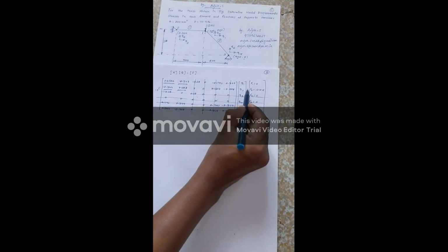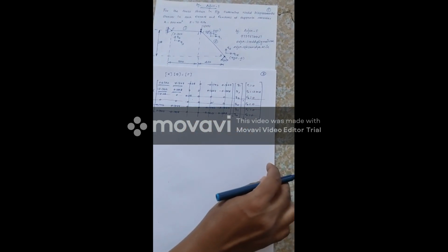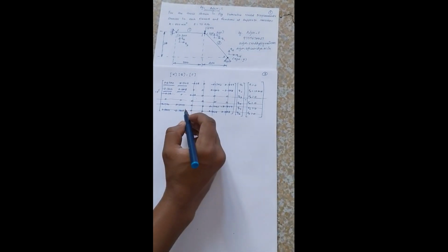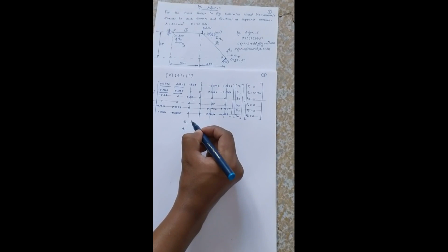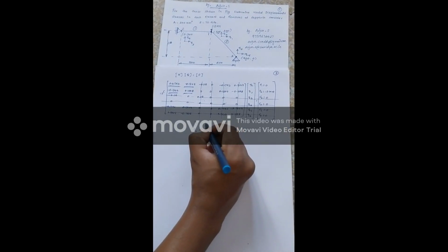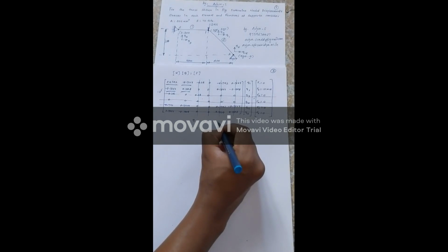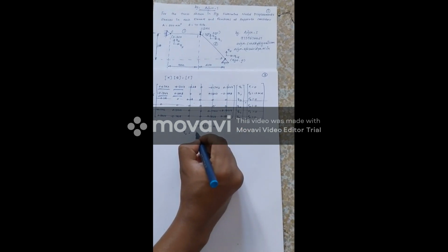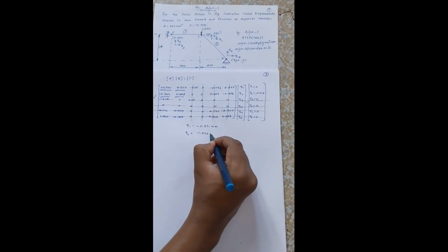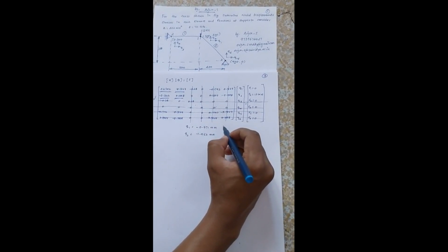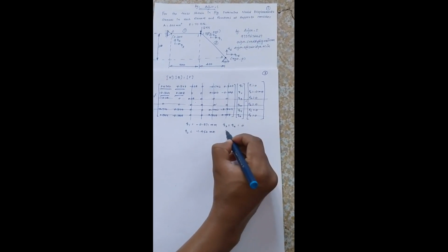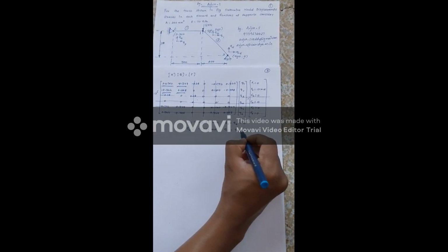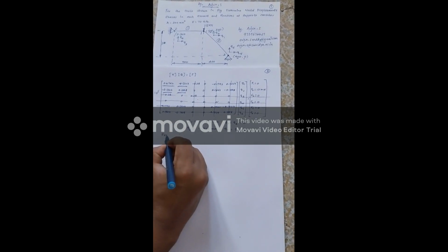and if you solve for this either by using a matrix method or by using equations, we'll get the 2 unknown values q1 and q2. So the value of q1 that we obtained is minus 0.571 mm, and the value of q2 obtained is minus 1.952 mm. And obviously since node 2 and node 3 are fixed, q3 will be equal to q4, which will be equal to 0, q5 will be equal to q6, which will be equal to 0 mm. Now we will see how to find the reactions at supports.